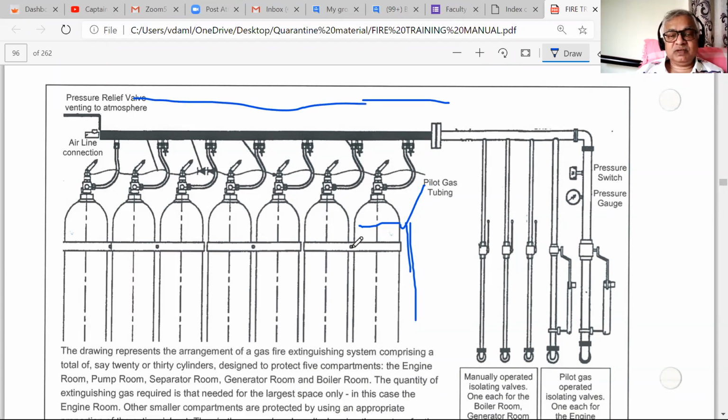What we do is we slacken this holding thing so the cylinder can move. These things are disconnected and the cylinder is checked with a gauge, which is attached here, the hook is here, and this is connected here. And you check the weight of one, go to the next one, next one, next one. That is another method which is done in dry docking.